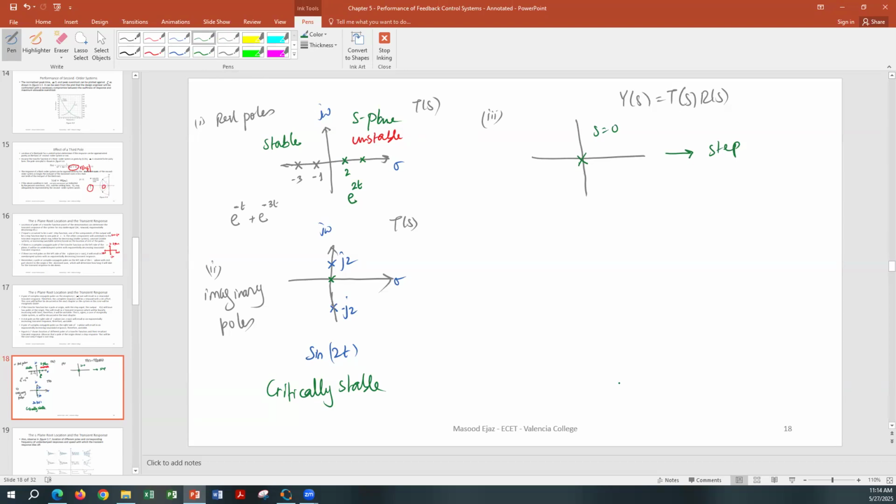And then if you excite that system with a step input, if Rs becomes a step as well, then you will have 2 poles at s is equal to 0, one coming from Ts, one coming from Rs. And again, your output is going to become unstable because you will have 1 over s square. And if you look at the table, actually you don't have to look in the table.